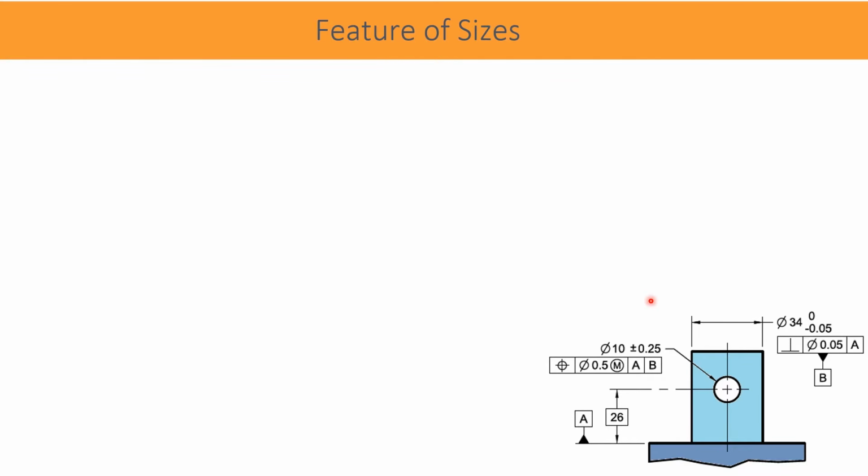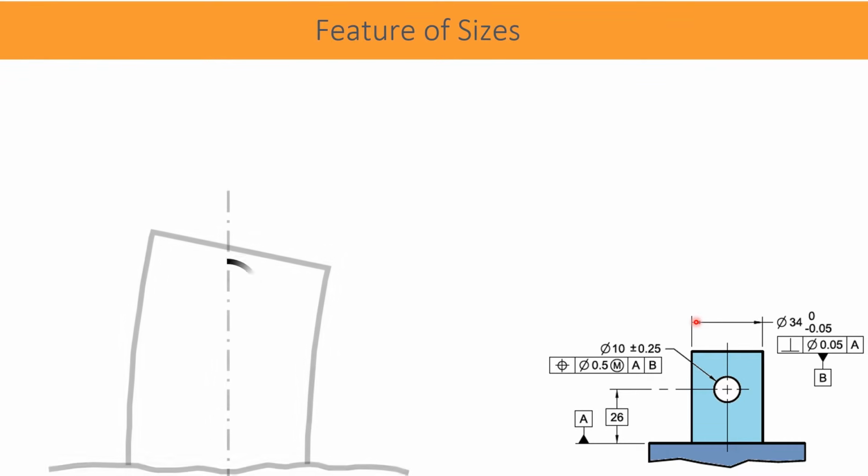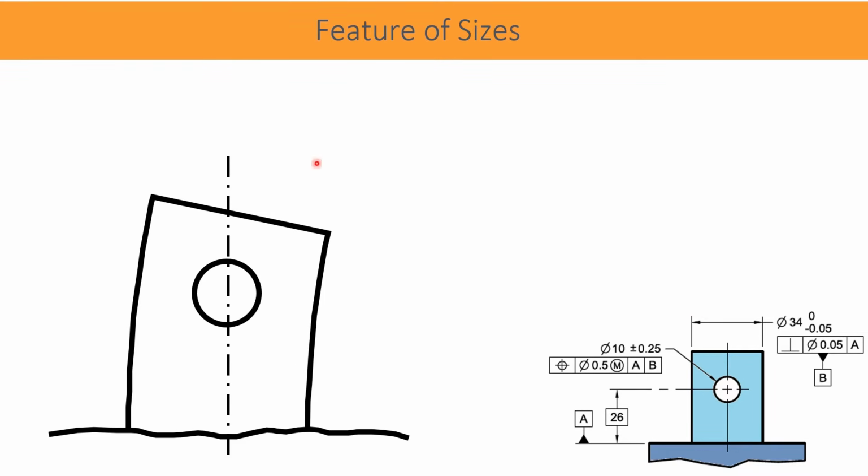In this given drawing, the size of the cylinder specified is 34, with no tolerance on the plus side, and at the lower side the tolerance is minus 0.05. Now let us think, after manufacturing, a certain size and shape of this part is produced, for example as shown in the figure. Surely it is not exactly the same as in the drawing for its size and shape.